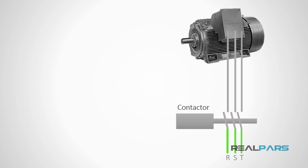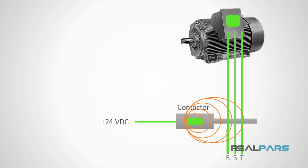A contactor has two main parts, a coil and some open or closed contacts. It works by connecting these three phases to its open contacts and then applying a voltage to its coil. The applied voltage creates an electromagnetic effect which closes the contacts, resulting in the three-phase power being delivered to the motor, turning it on. So by using the contactor, we can connect and cut the electricity supply, which in turn results in the motor being switched on and off.